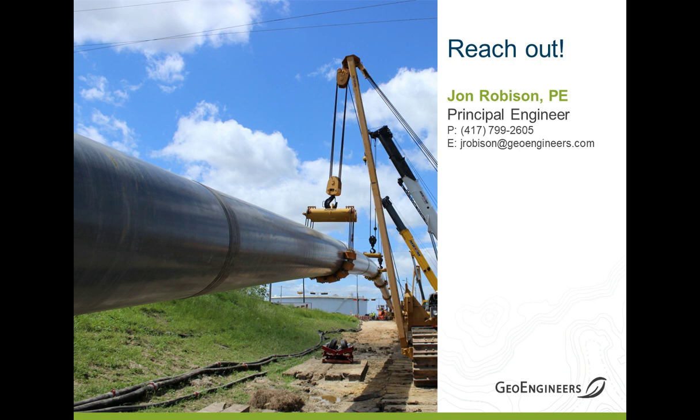There may be others. It's not a commonplace thing to post-grout. But if you're near the ground surface or underneath a critical piece of infrastructure and you need to do that, you can do it. It would have to be, I think, with casing pipe, unless you had a high pressure line that you were working with. But if it was a gravity sewer or something like that, I think you could put ports in that.